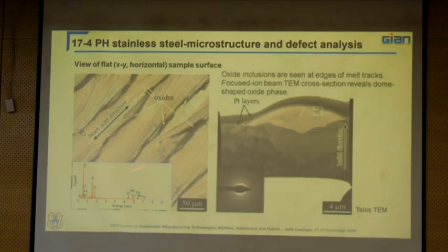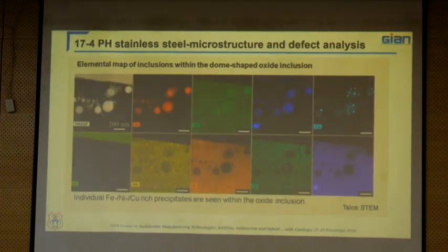They analyzed in depth to understand why that deformation occurs and what kinds of defects come across in the reused powder particles. If you see, they analyzed with TEM, and they were able to observe oxide inclusions in each layer. This is one layer, these are multiple layers, and in each layer they could see and understand the oxide inclusions. Because of these oxide inclusions, you end up with difficulties or different oxide contaminations in your printed parts.